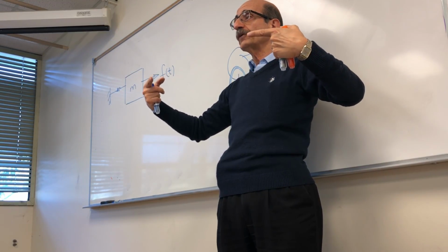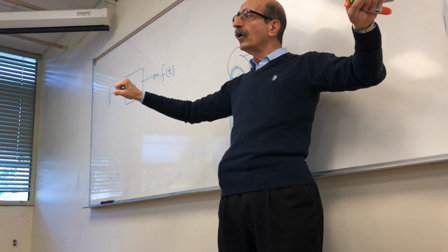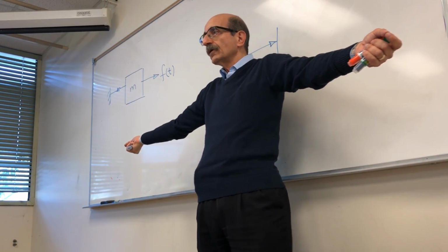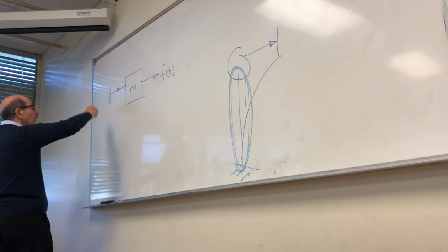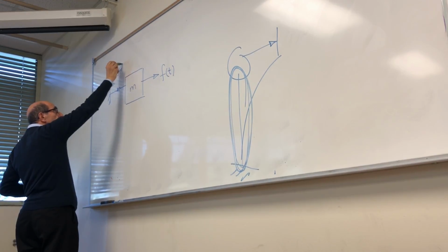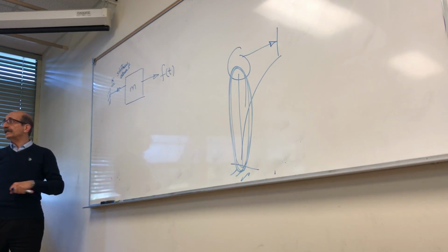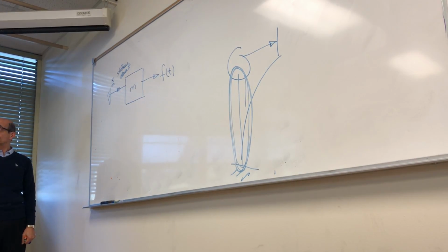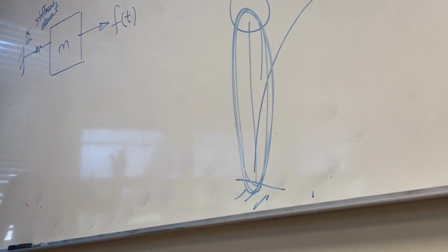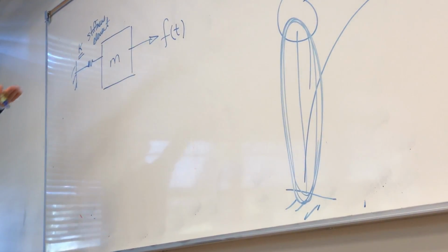Does that remind you of something? In strength of materials, you have a force that is acting along a bar, and that's all that does, right? So that represents a spring. So this force is nothing but what we call a spring or stiffness element that is resisting that motion. That's what we refer to as the force that resists deformation. Deformation takes place in only one direction, so this is like a spring.